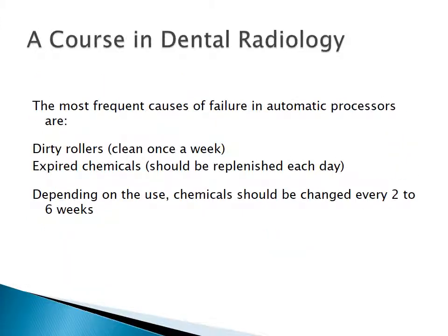The 2 most common failure points on processors are dirty rollers, meaning they just are not cleaning that processor once a week like they should be, or they're trying to save money and their chemicals are expired. They should be refreshing their chemicals at least daily.